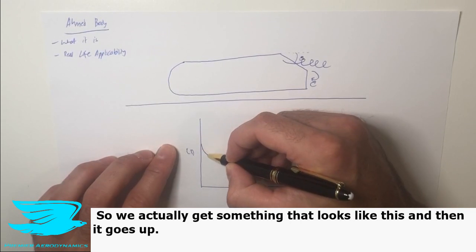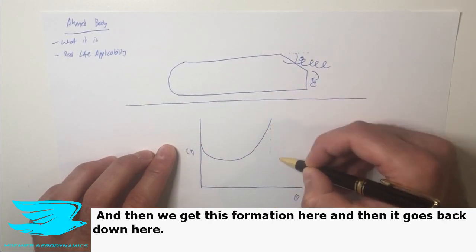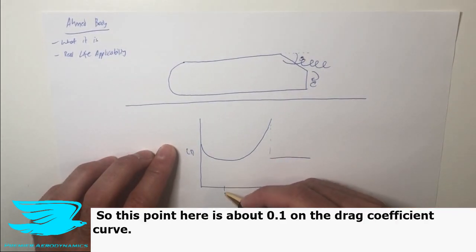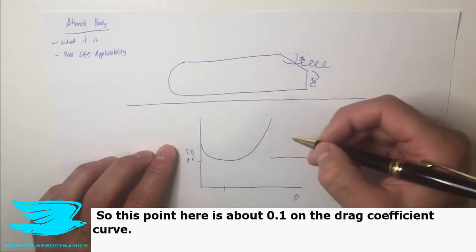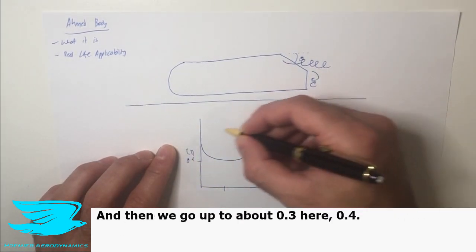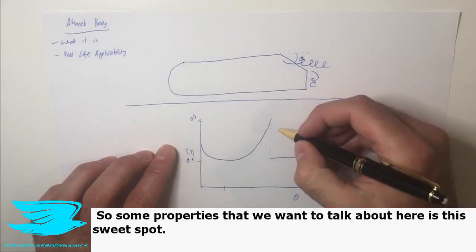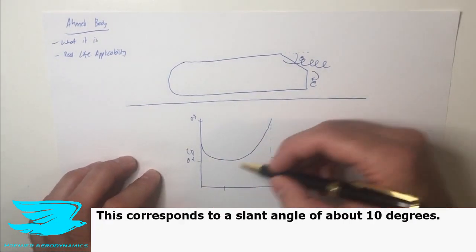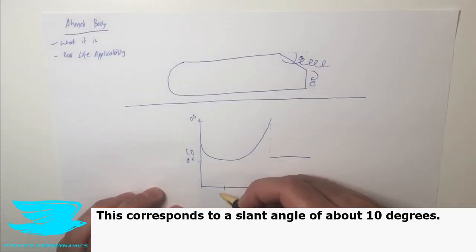So we actually get something that looks like this, and then it goes up, and then we get this formation here, and then it comes back down here. So this point here is about 0.1 on the drag coefficient curve, and then we go up to about 0.3 here, 0.4, then this drops back down. So some properties that we want to talk about here is one, this sweet spot. This corresponds to a certain slant angle, and that's usually about 10 degrees.